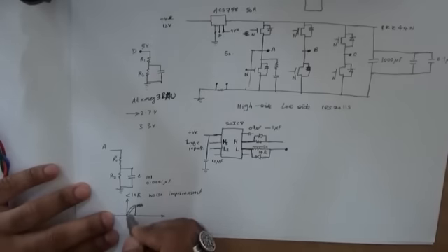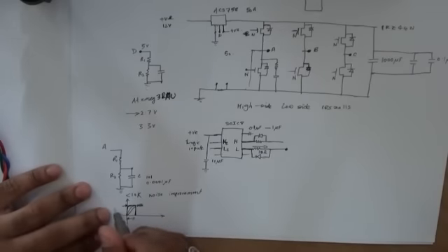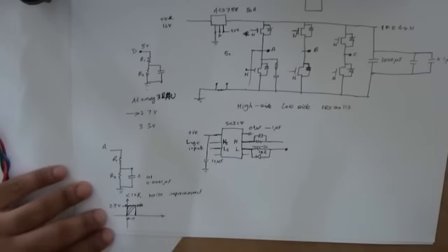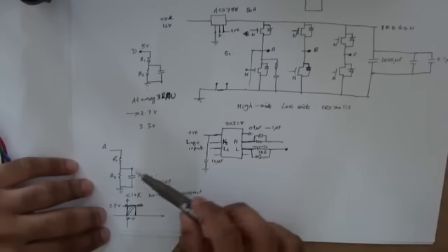You want the pulse to show up as quick as possible with the least amount of decay, and the maximum level you want to see on the pulse is somewhere around 2.7 volt. So just keep those words in mind.